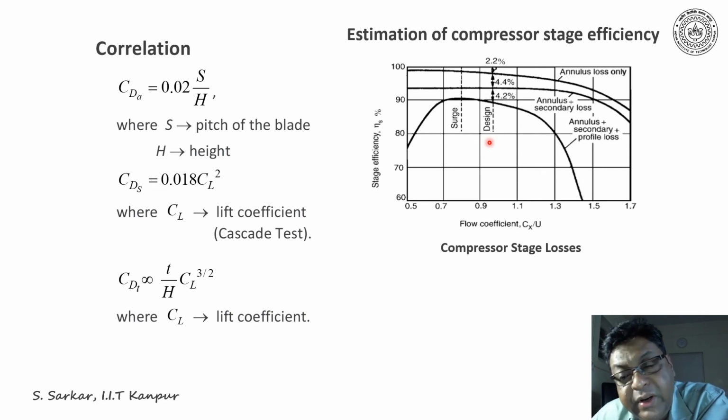Now it should be noted that profile loss dramatically increases after certain value of flow coefficient. Thus, if I increase phi, the contribution of profile losses would be much higher corresponding to other two.